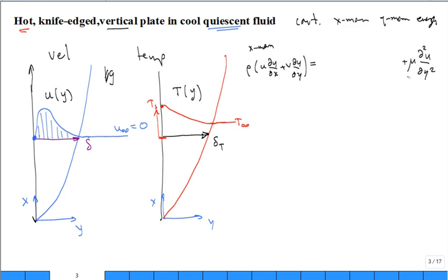Well, we're going to have a body force term minus rho g, meaning here I have g and it's in the negative x direction. And rho times g, isn't that our body force term in our momentum? But there's one other term, and it's the rate of change of pressure with respect to x, and we'll put a minus sign on that. That's our x momentum equation. If there's a pressure pushing it, a pressure difference.